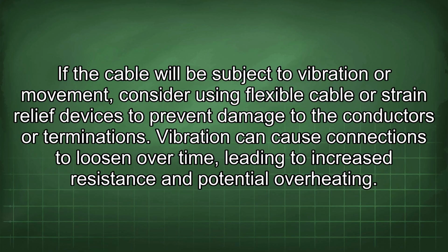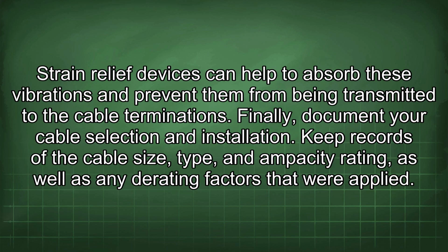If the cable will be subject to vibration or movement, consider using flexible cable or strain relief devices to prevent damage to the conductors or terminations. Vibration can cause connections to loosen over time, leading to increased resistance and potential overheating. Strain relief devices can help to absorb these vibrations and prevent them from being transmitted to the cable terminations.